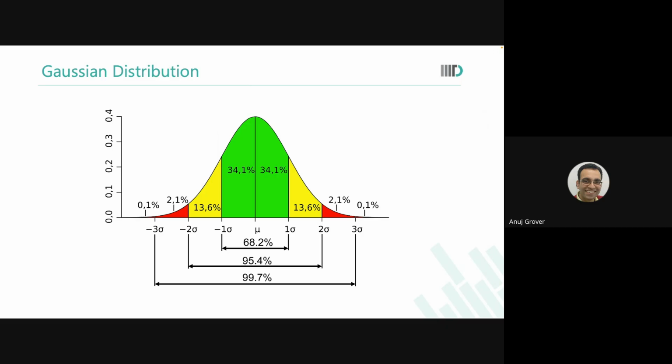Is 99 the number everyone is getting? So in a 1K words memory, 1K cross 32, 1K 32-bit words memory, 99 words. So 99 cells which could be randomly distributed. In the worst case, those 99 words would be impacted. So out of 1000 words, 99 words will fail. Do you think that is okay with you? Do you think you will get 100% marks when you qualify plus minus 3 sigma? You can't even make a 1K word memory work.